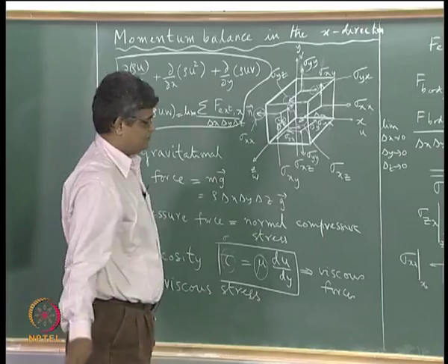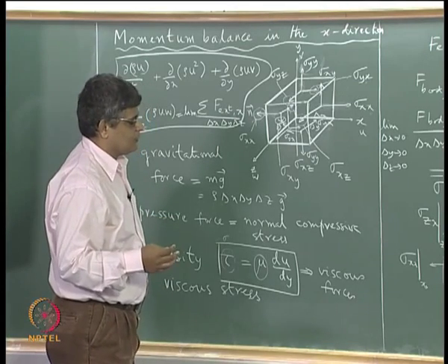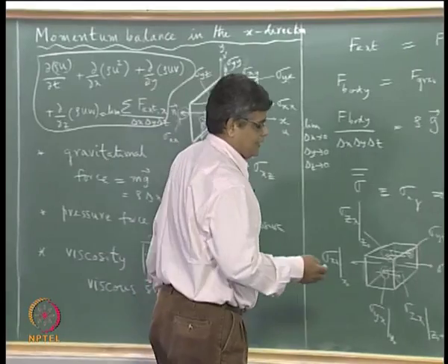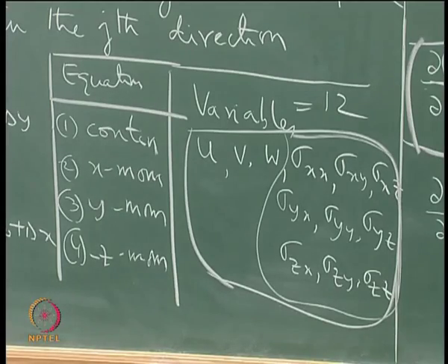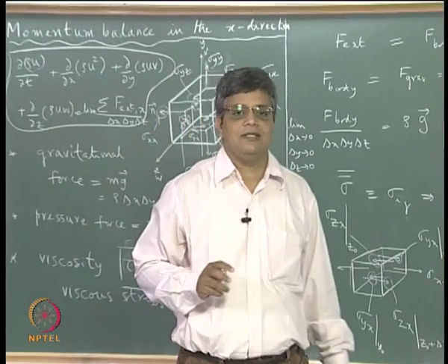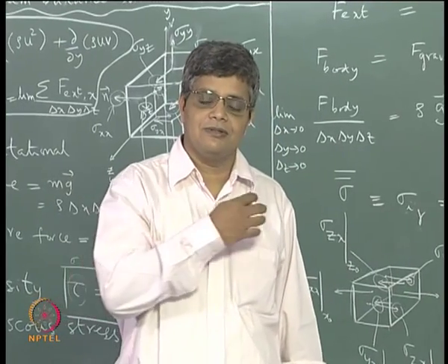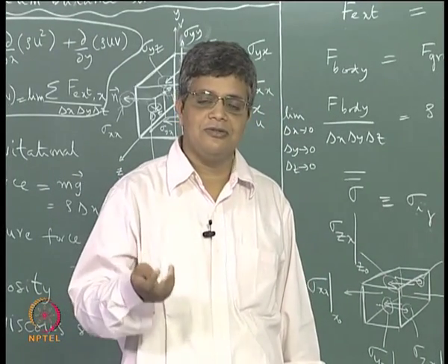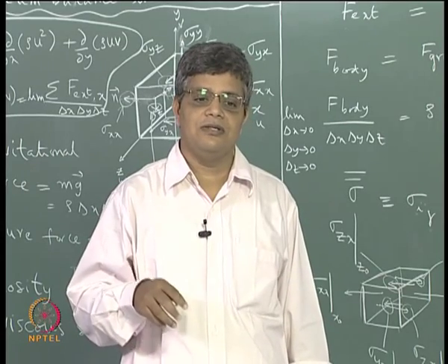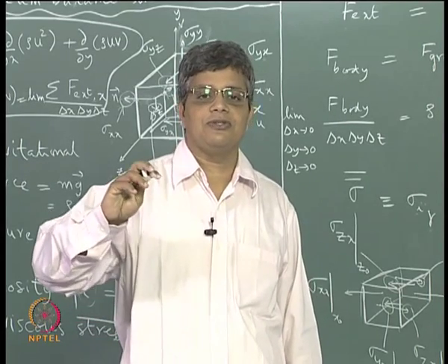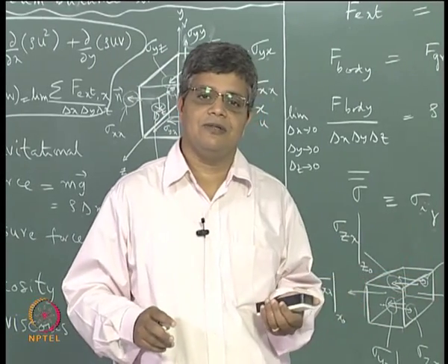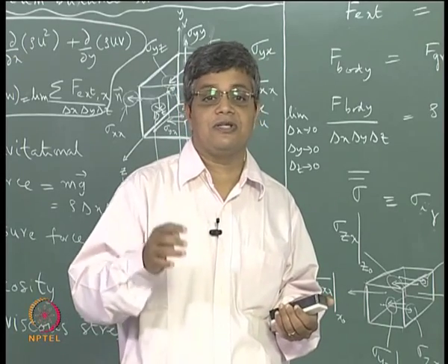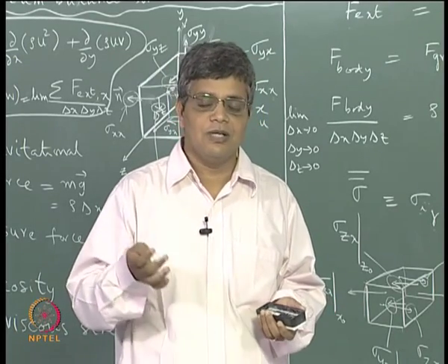Okay, so we now search for a constitutive law which describes the stresses within the fluid which are part of the momentum balance equation. We do this by drawing an analogy with solid mechanics, because solid mechanics is faced with the same situation, and there you bring in the equivalent of Hooke's law, where you say that the stress is proportional to strain. Okay, so here we bring in the same kind of argument. We say that the stress is proportional to the rate of strain,